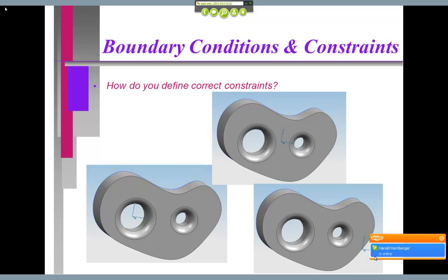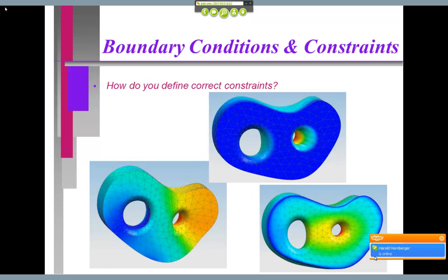The corner in the center of that cylinder is trying to suggest that we are going to constrain the inside of this cylinder as a constraint. And this one over here on the lower right, it's on the edge. When it came up and asked what do you want to constrain, we grabbed an edge and it said, no problem, I can constrain it. So based on just the constraints, we're going to get very different images, okay?